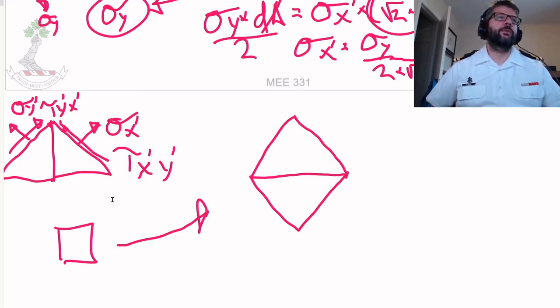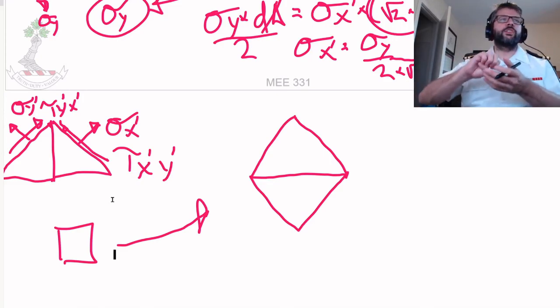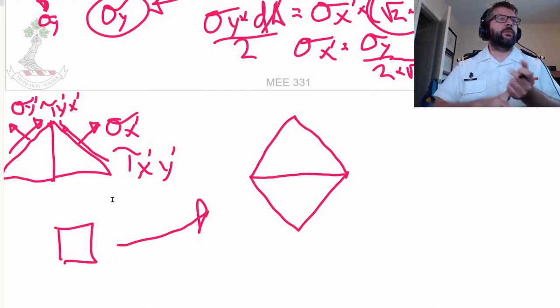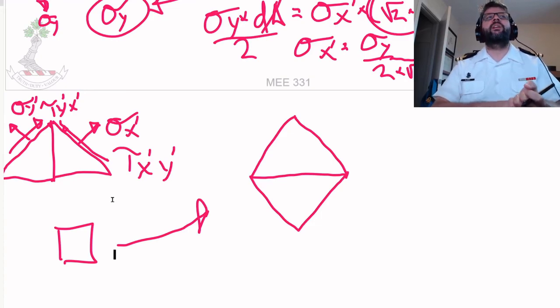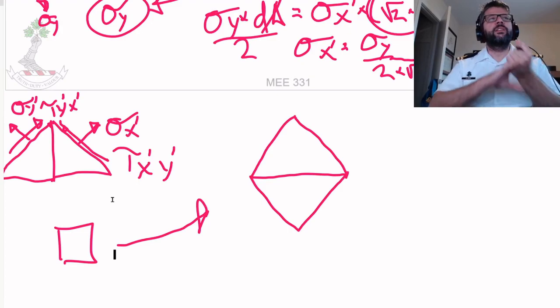We'll touch upon this quite a bit later on in the course when we get to the stress transformations, because if we calculate a stress state that has shear stresses all over the place, it turns out that we can figure out a combination of rotations about the x-axis, the y-axis, and the z-axis that will transform any stress state that has shear in it to a single stress state that has only normal forces applied to it.